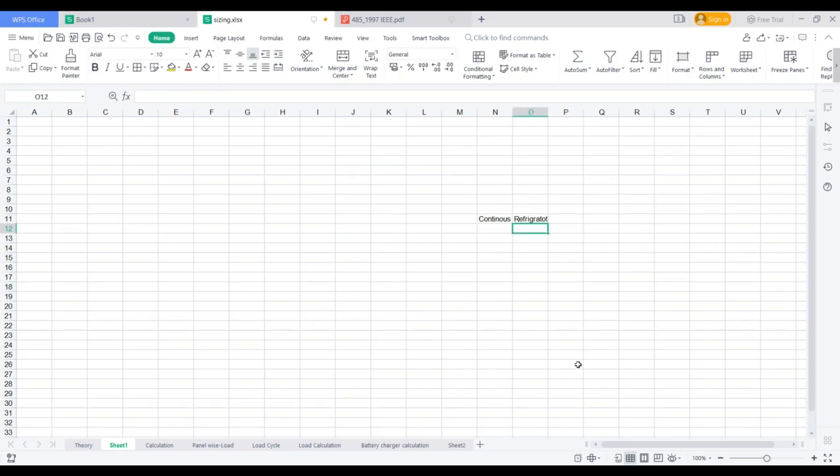And for the next loads, I cannot predict when the AC power will be lost. If it is morning, there is no need for lights. If it is evening, definitely I require the lights. So it's your analysis: you have to take the lights as continuous, or as non-continuous.